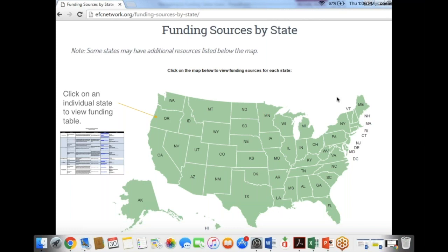And if you can, while you're mapping, note how old that asset is. Is it 100 years old? Is it 50 years old? 20 years old? Just your best guess at that, with a map, means you can do an awful lot of planning off just that bit of information. And the thing again not to do is to try and get that down to sub-millimeter accuracy. Some people might be tempted to do that, but as Heather said, a basic map is a very good idea.